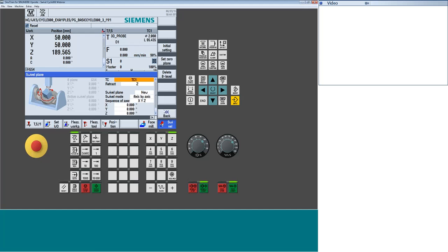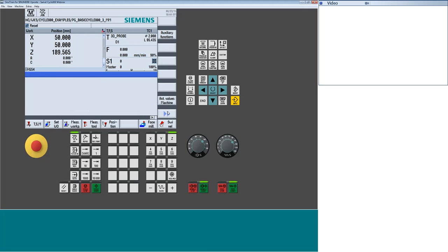So what we've done is we've incorporated 2 key functions within our Measure Workpiece tools. And those of us that have been using our control, or maybe seen some of my earlier webinars, would be familiar with the Measure Workpiece function as far as setting a basic 3-axis machine. And those are the same tools you'll use when it's time to actually define the 0. But the first thing we need to do, and I'm going to put a probe in my spindle. I happen to have one, so I don't need to tool change it. The probe is in here. That's great.